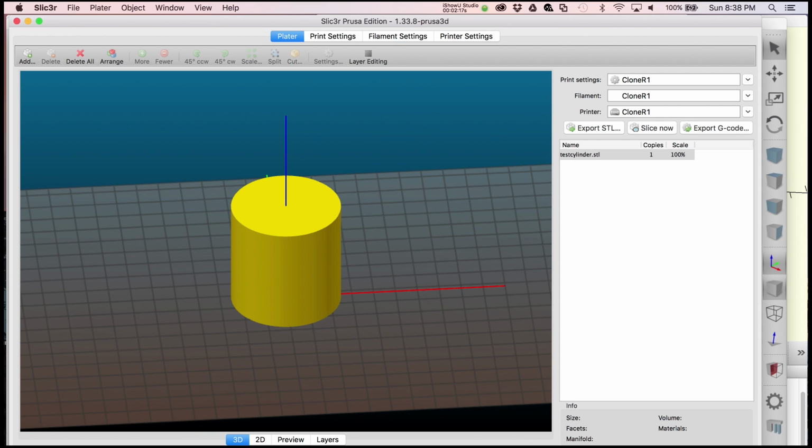The way the program works is it essentially rewrites all the speeds in your file. So it doesn't really matter what speed you set the print speed at, but it has to be the same speed for the whole print, outside the first couple layers where you want to have a good bed adhesion and where you're not really going to be running this process anyways. You want it at the same speed, and you don't want anything set like, hey, I've got a really thin tower, slow down. All that needs to be turned off. Inner parameters, outer parameters, everything needs to be the same. Now, like I said, it doesn't really matter what that speed is set at, but you probably want to make it a reasonable speed within your printer in case you mess something up, and you don't want to set that you're going 1,000 millimeters per second. Your printer will not be happy if it doesn't work out.